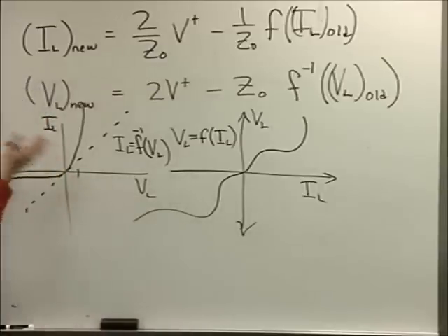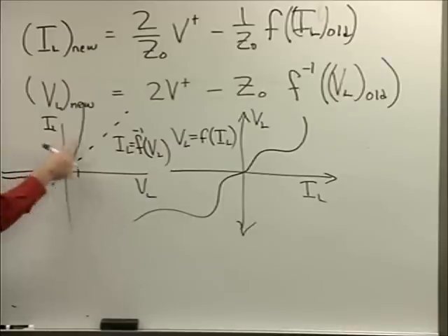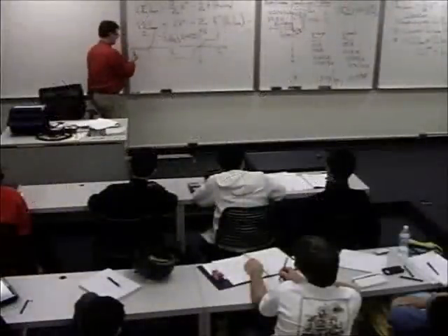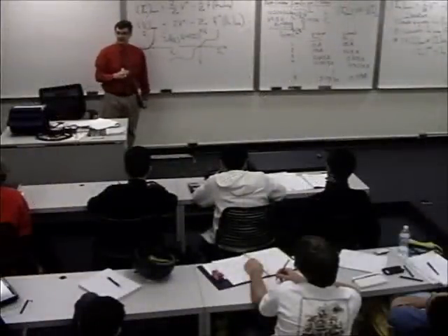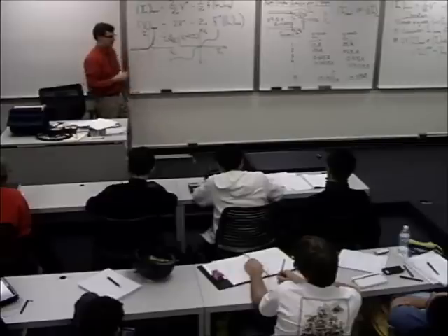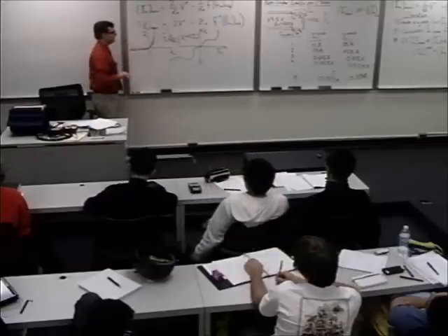This is a memoryless device, but it's a highly nonlinear device in that there's no temporal relationship or time variation that you have to take into account. You don't have to take derivatives or anything like that. But the constitutive relationship between voltage and current across the terminals of the diode is highly nonlinear. And that, of course, is why it's interesting, right? You can do a lot of really neat things with that behavior that you can't do with simple straight lines.